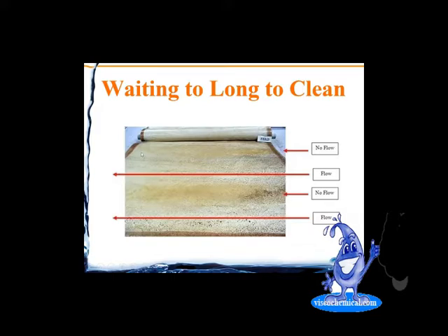So this element is said to be channeled. Because of that, this is going to make our cleaning very, very difficult, especially if you're just using a standard cleaning procedure that says something like mix up your chemicals, get the temperature right, get everything dissolved, then circulate for an hour, soak for an hour, circulate for an hour, rinse, and you're done.